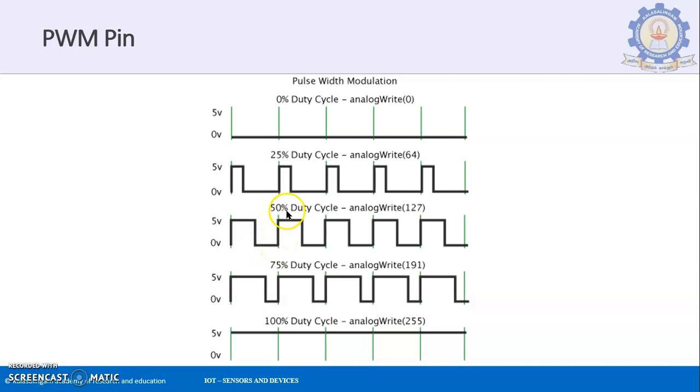So never relate the 50% to the off time. It is always 50% with respect to the on time. 100 minus that percentage value is the off time of that particular signal when it comes to duty cycle, when it comes to PWM. Okay. So this is my 50% on, 50% off. Which means that it is getting equal time on, equal time off over here.